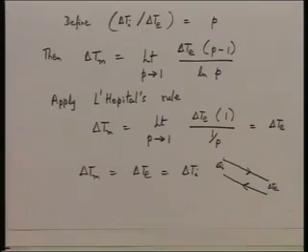So, for the special case, the temperature profiles tend to be straight lines, two parallel lines, and delta Tm becomes equal to delta Ti or delta Te. So, this is one special case of counterflow worth talking about. Now, let us move on to cross flow. We want to now get expressions or get values for the mean temperature difference in cross flow.